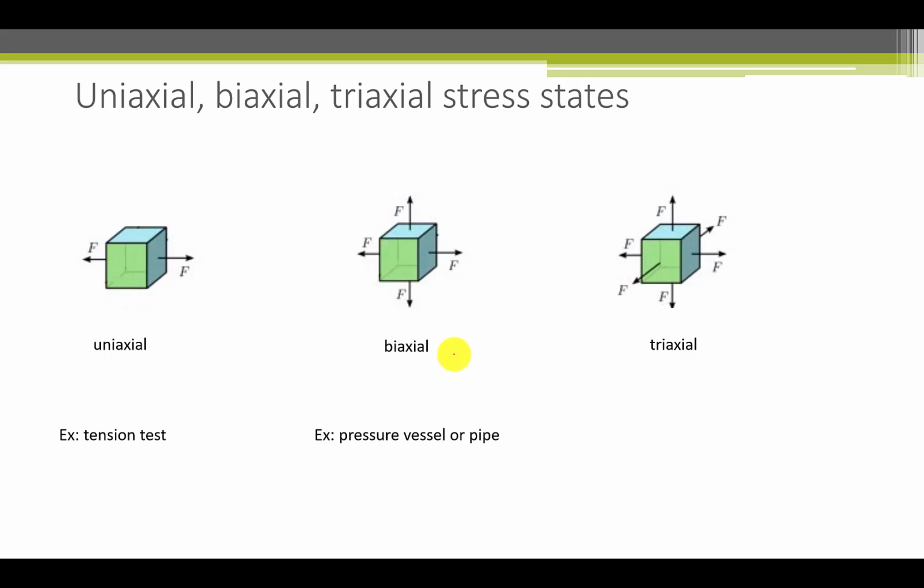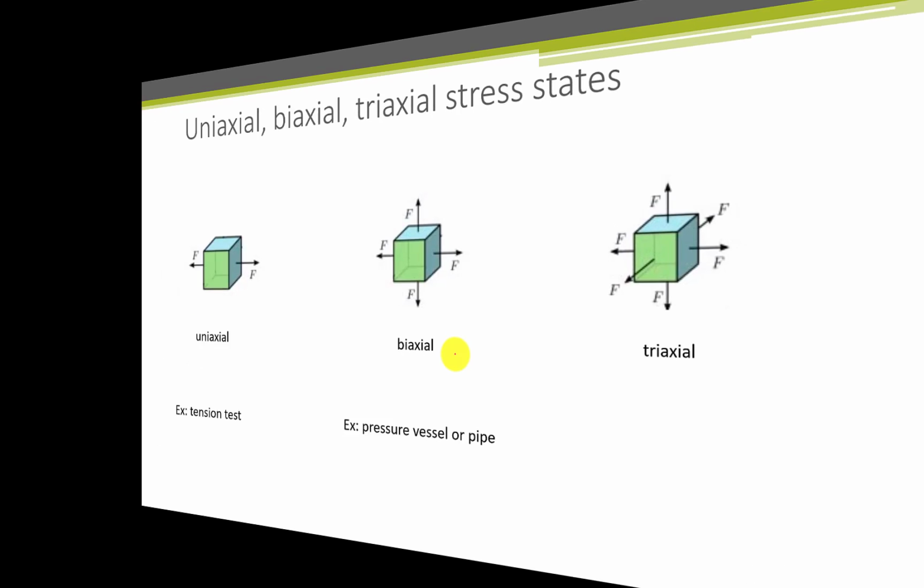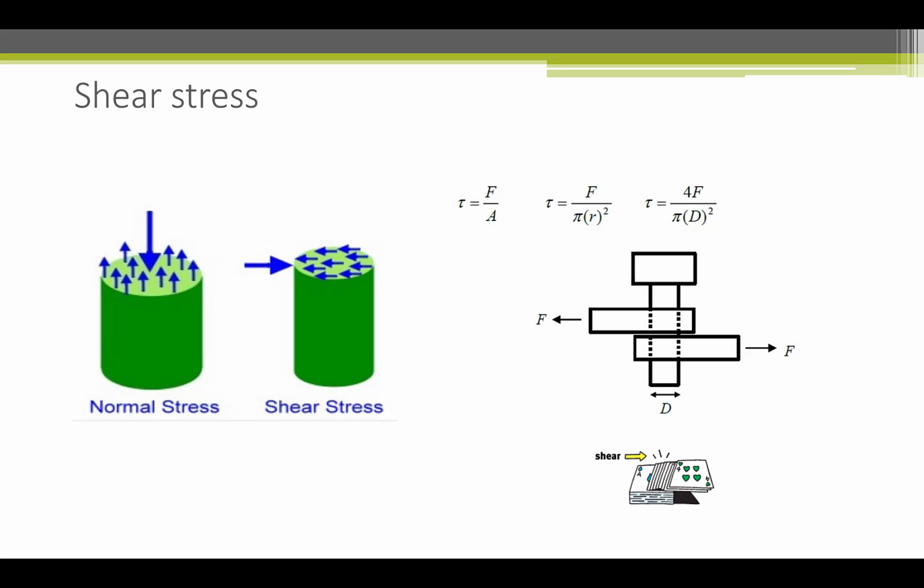It's often the case that forces act in more than one direction at once. A classic example is a pipe or a pressure vessel. These have stresses which go around the girth and are called hoop stresses, but there is also a stress that is longitudinal with a pipe or a vessel. The plate used to construct this equipment is subject to biaxial stresses. Finally, the most complex of the stress conditions, which act in three directions simultaneously, are called the triaxial stress state. Usually, finite element analysis is needed to supplement understanding of the actual stresses and directions associated with the complexities of the involved geometries.